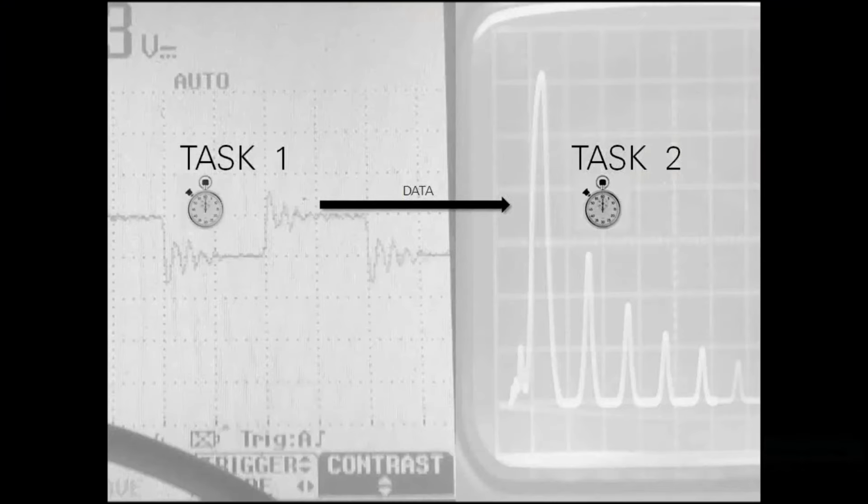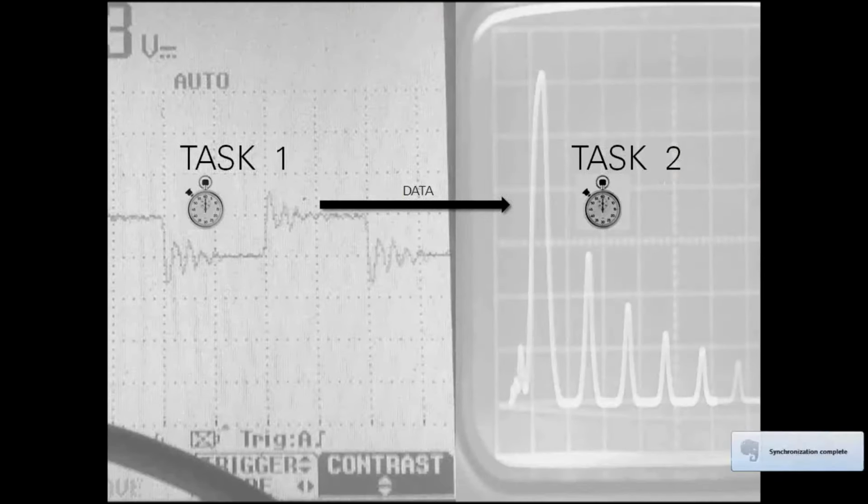This situation is pretty commonplace, and a very good example of this is the tasks of acquiring data and analyzing using fast Fourier transform. The acquisition is clock based, which means it generates data at a constant rate. However, the analysis is done in software, which is an operation that is scheduled by the OS. So if the analysis code slows down, we will definitely miss samples. So we have a generation code that generates data continuously, and we have a processing code that is determined by various OS parameters, which is non-deterministic. Now, how do we tackle this kind of situation?